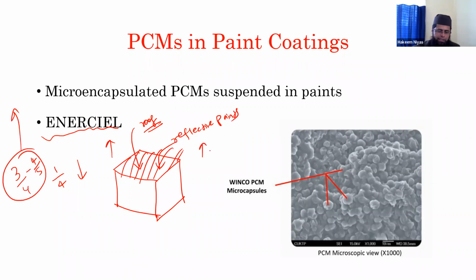This is a very easy technique in an existing house. We just use a white reflective paint, which is available commercially in all the brands in our country. By that way, we can see a nice 4 degrees Celsius decrease in the room temperature. So this is one thing.